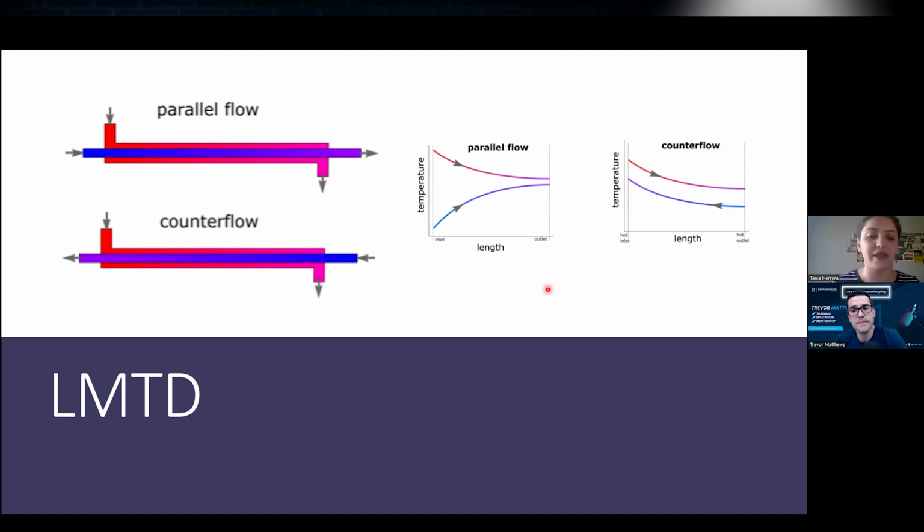Yeah, sure. For instance, when we consider sensible heat, so refrigerants that don't have a phase change, we have seen that counterflow is the one that is more efficient. That would be like a glycol system, I would say. For example, I work on a secondary glycol system in the supermarket where I work. You would see a lot of that. That's exactly what it is, the counterflow. The parallel flow, I don't see too often, but I know I've seen it in a few applications.